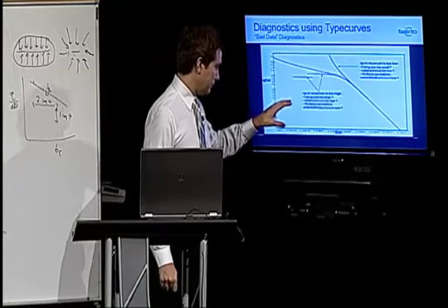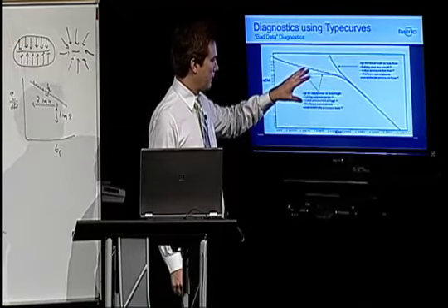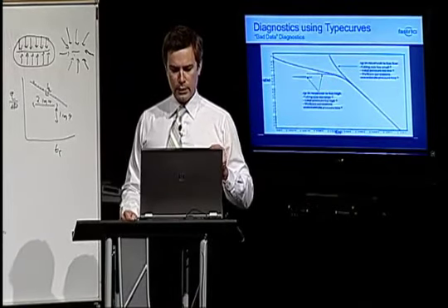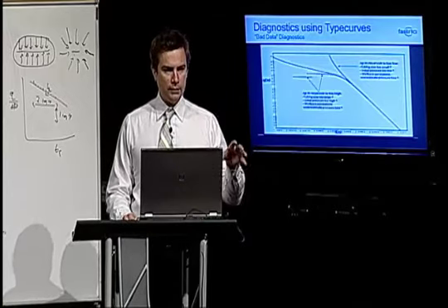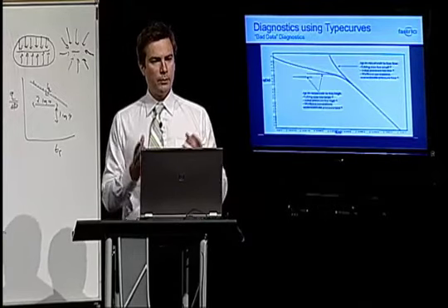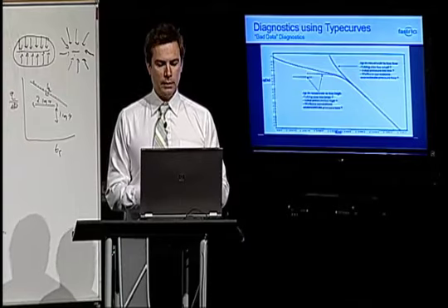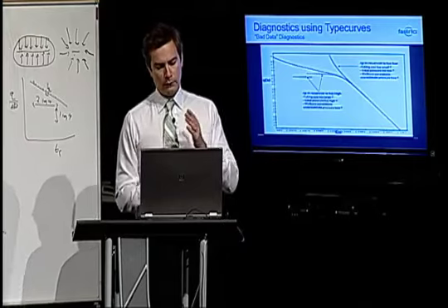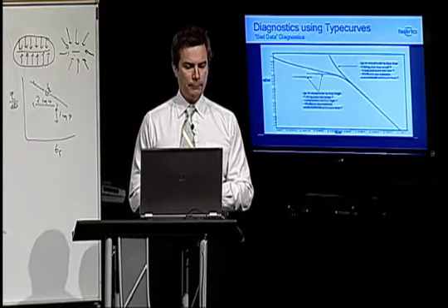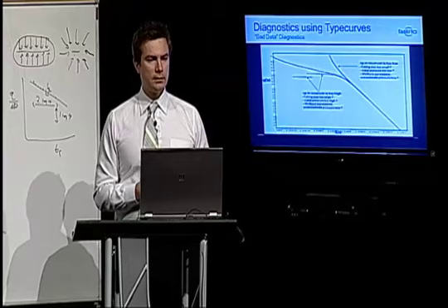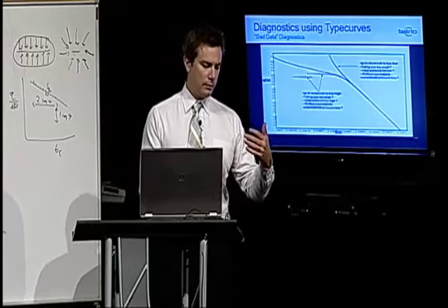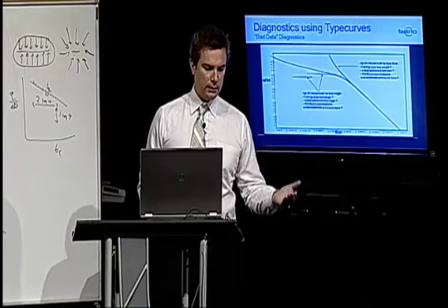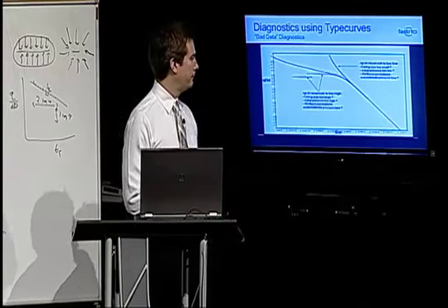So one of the places where it gives us the opportunity to make mistakes with flowing pressures is when we take a measured pressure and convert it into a calculated pressure, but we have to do that. We don't have a choice. But it introduces the possibility of making errors, and that's kind of what this is all about. So our flowing pressure may be measured at the wellhead, but we have to convert it using a nodal analysis. We have to calculate the pressure loss in the wellbore so we can convert it to a bottom hole or sand face pressure.